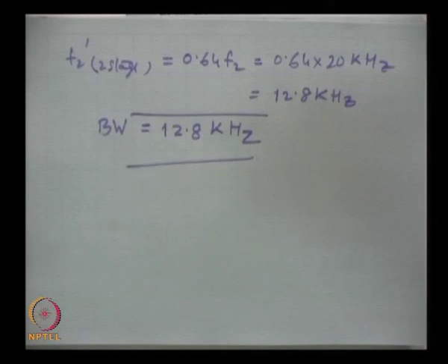The physical reasoning we can get from the fact that gain bandwidth product is constant. So, we have seen numerically that while the gains are enhanced drastically, the bandwidths fall. So, in a multi-stage amplifier, to maintain a reasonable bandwidth, we have to start with individual stages which should have much higher bandwidth than required in the application.